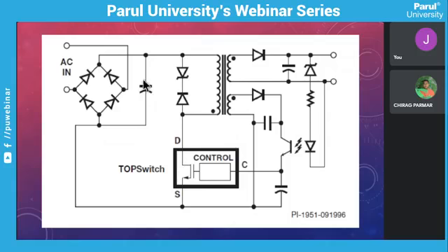So how it functions is that the DC voltage is applied to the primary. The switching IC switches the controller, and that DC is converted into pulses. Those pulses are fed into the primary, and while the switching period is off, the remaining energy stored in the primary of the transformer is fed back through this normal UF diode.